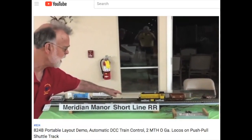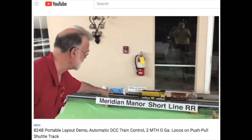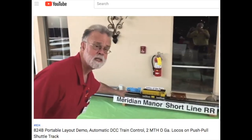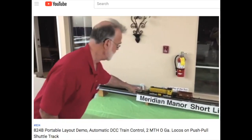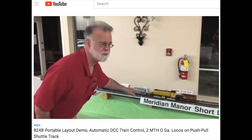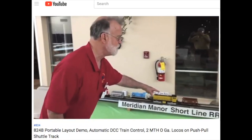This is running on a time delay. It's running for about 13 seconds and stopping. Since there's no detector, it's using time delay. There, it stopped it. Now the controller will wait about 13 seconds, and then it will back this one up, and you can see it started going back.